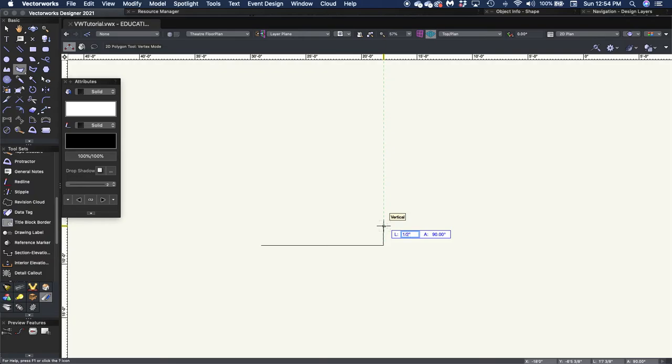The inches is the quotation marks, which is our shortcut for inches. I'm going to hit enter. It's going to give me my circle again. I'm going to click again, and I know that that line is at that exact distance.